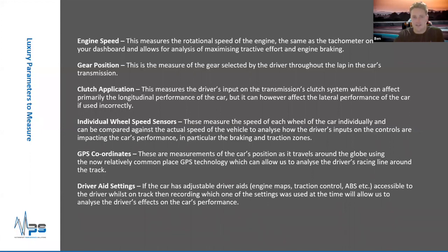If you've got a manual car with a clutch pedal, it's a good idea to track how the driver applies the clutch. I mean, even at touring car level, you won't believe the mistakes that go on there. It's not mistakes, it's that a driver doesn't realize they're doing it. It's very easy to rest your foot on the clutch in high G situations. So that's a good one to watch.